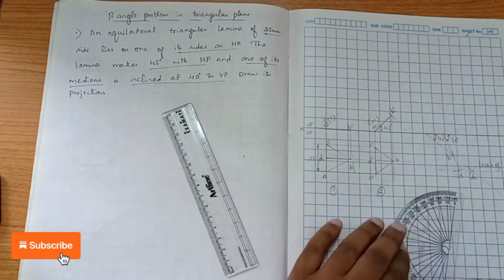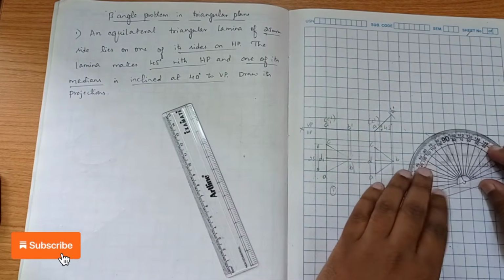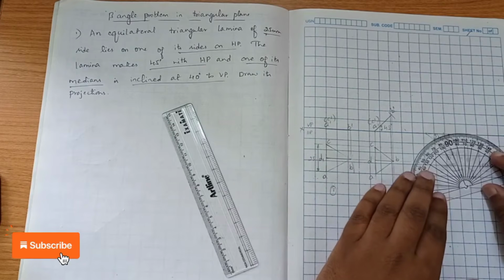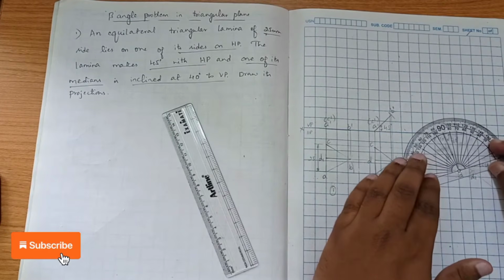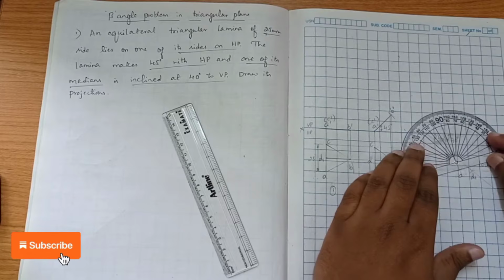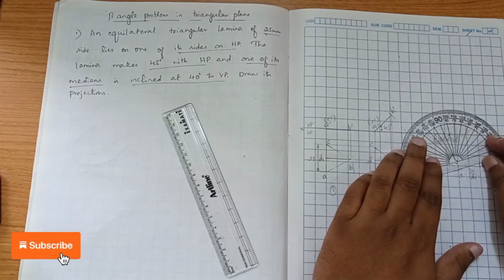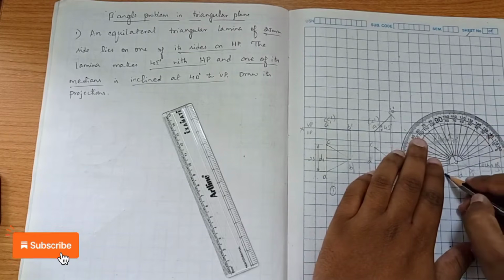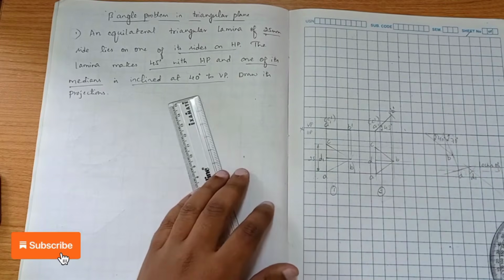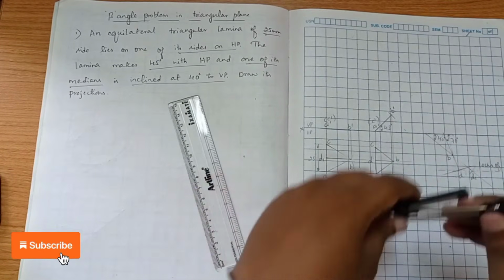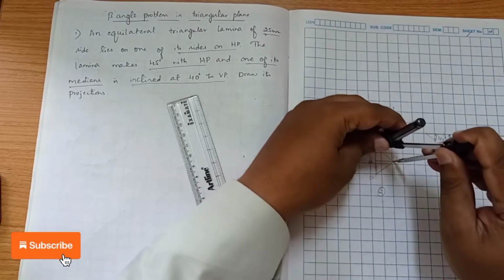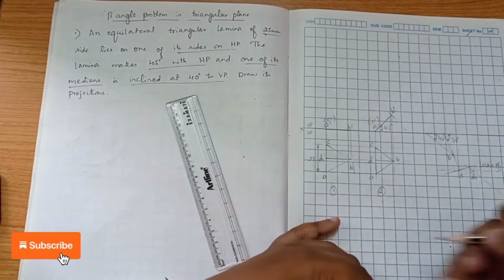So what I will do initially, with respect to this BD line, I am going to merge this 90 degree line and draw a straight horizontal line here. After this, by cutting the arcs, we have to transfer this diagram. So this diagram we have to copy.